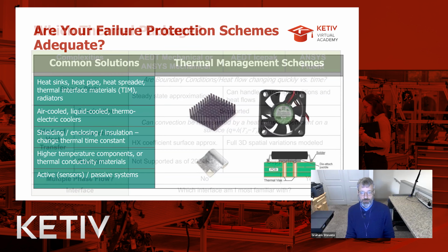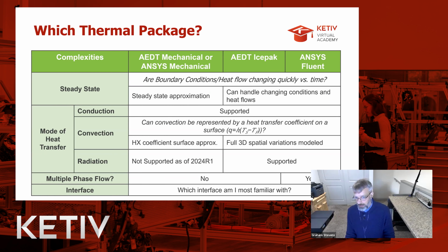What's going to work? And so in the Ansys universe, there are 3 different thermal packages that do this kind of thermal modeling. Typically for the electronics area, we focus on AEDT IcePack, because IcePack is a package that's been special purpose designed for electronic box cooling. So there are fans and heat sinks that are automatically created, or that you can drop in the design, a drop and go design philosophy.